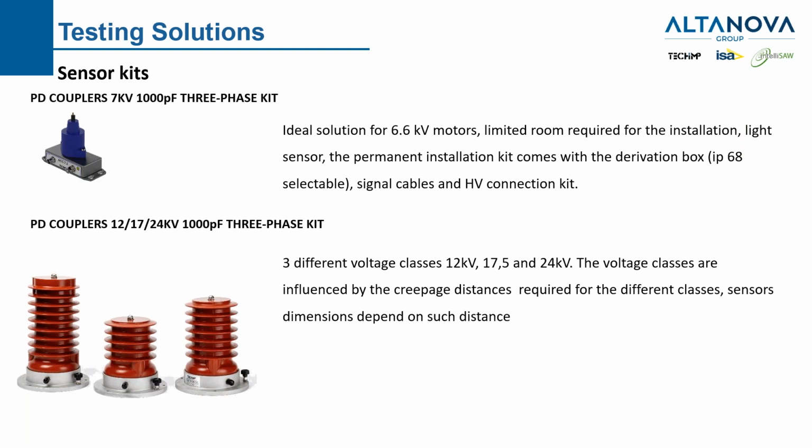If I have a certain working principle, it will be better for me to use the 80 picofarad. If they have another bandwidth instrument, it will be okay to use the 2 nanofarad. But with our approach with the time frequency map, there is no more problem with the capacitance. The sensor is not used as a filter, but to get all the information, and then in case we filter the information with the TF map or hardware filtering.